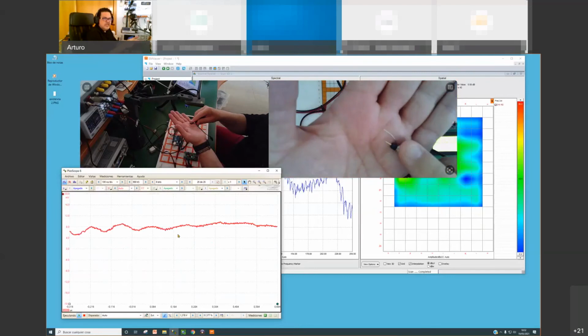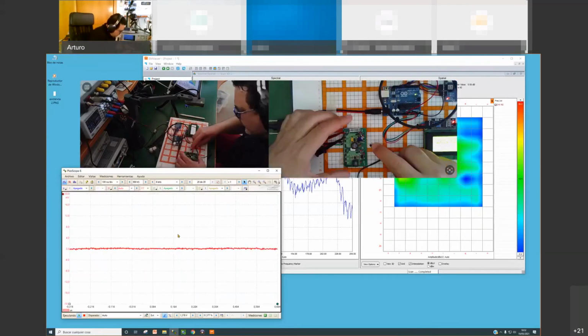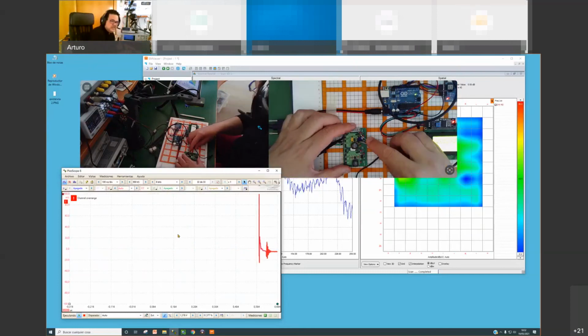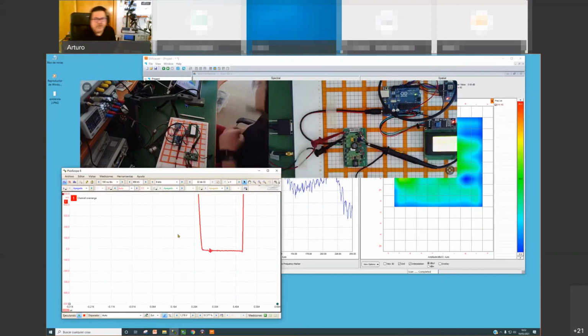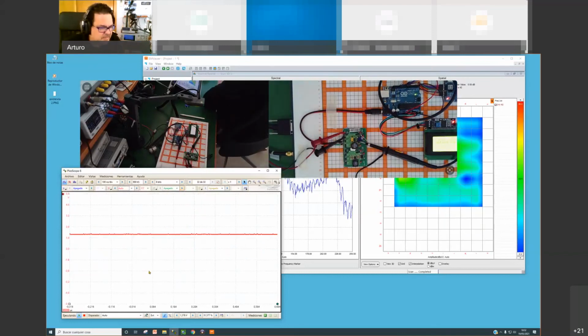And with this technique, we go to the circuit and we connect the probe to ground and to the switching device. Okay, this way. So now we are measuring the switching activity in my device. Let's take, I don't know, 5 volts peak to peak. Oh, sorry, 5 volts, no, this is too much. Let's go to 1 volt peak to peak.